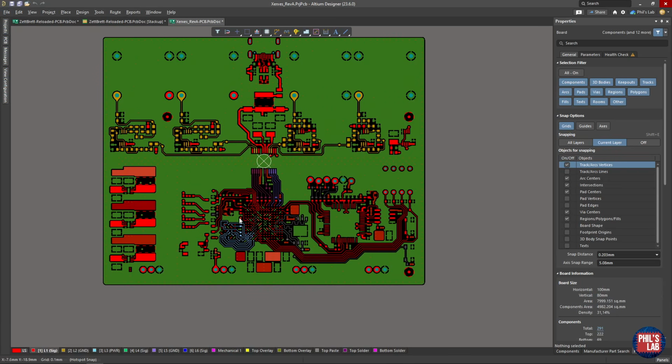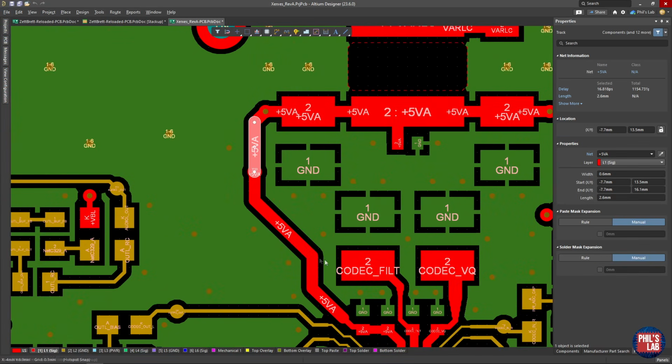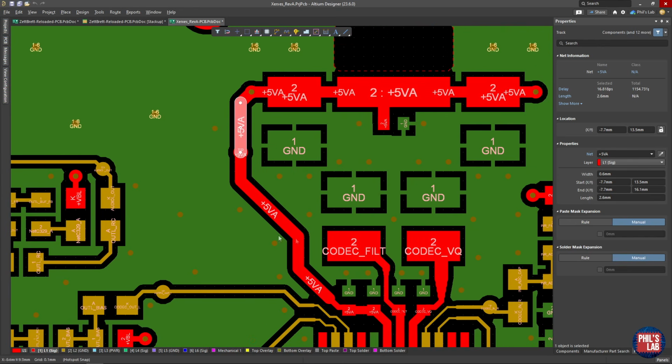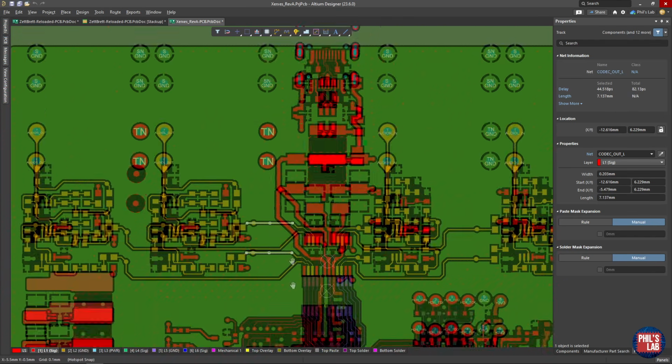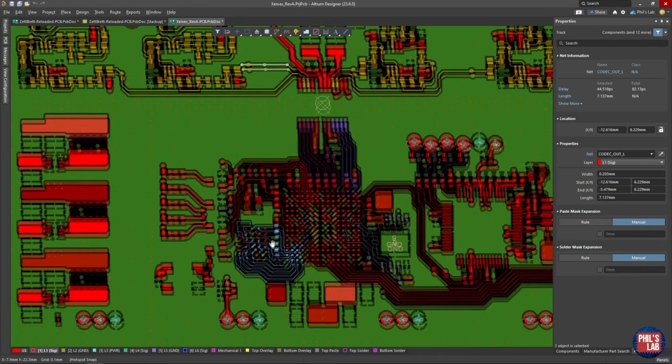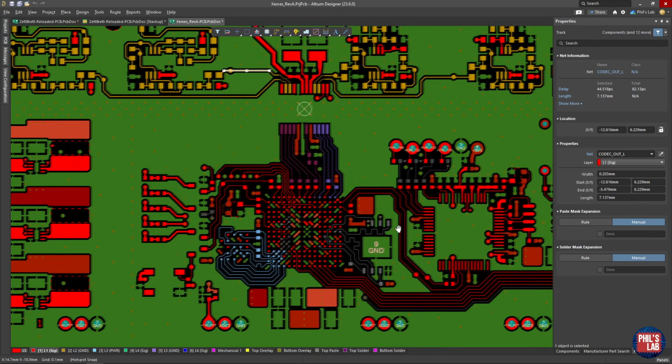This is why in power distribution systems, we will typically use wide traces, something like so. This is a 0.6mm trace, and you can see immediately this is a power delivery trace compared to these thin signal traces, and we also want to keep them as short as we can. Length has to do with inductance pretty much directly, therefore we want wide traces, short traces. And this is true for decoupling, it's true for the whole power distribution network.